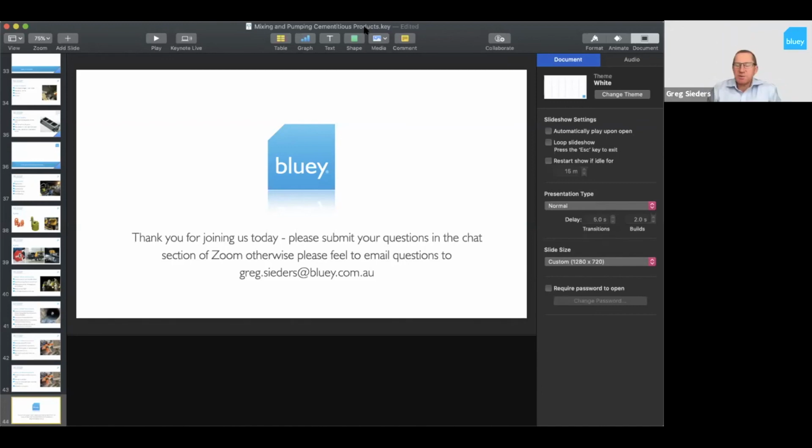You want to just check as well, Daniel, with your grout supplier, to make sure that whatever you are adding is suitable and compatible with the grout and doesn't have any adverse effects. Typically, if it's a powder admixture, it would be added by your supplier and supplied as a pre-packaged mix, I would assume. But you should always check if you're adding anything extra.